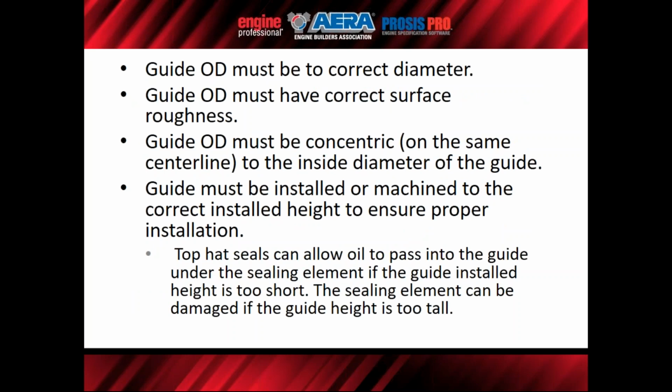That was actually an issue with the earlier ring and band type seals, the guide ODs. There was a lot of variation in casting, and the ring and band was fairly flexible, but there's distortion because of spreading that material so far.